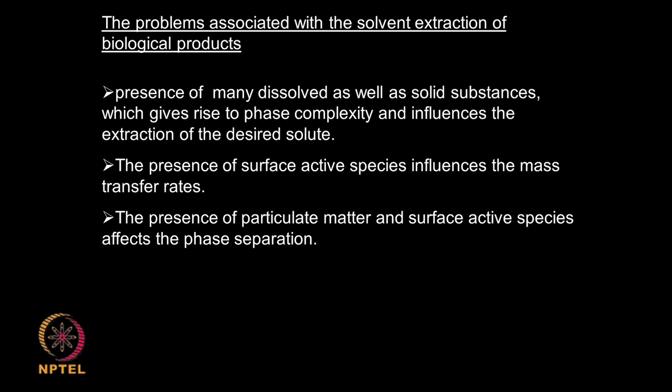Okay. So, the problems associated with solvent extraction: sometimes you may have many dissolved solid substances, so you will not be able to get a good phase separation, there will be complexity of the phases. So, the extraction of the desired product becomes difficult. There could be some surface active agents like surfactants that may be present in your fermentation broth.